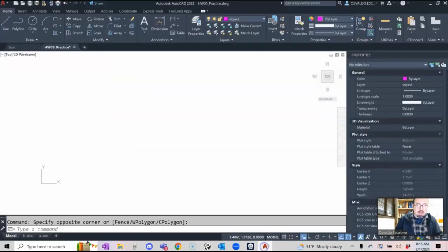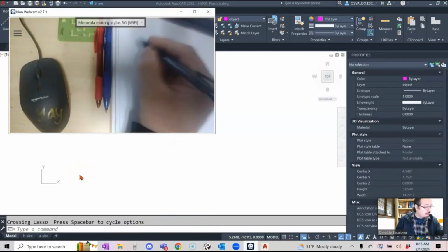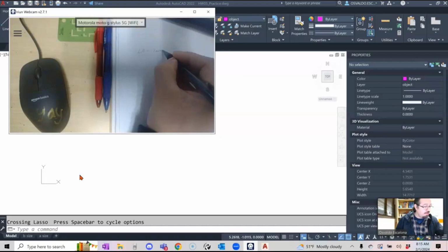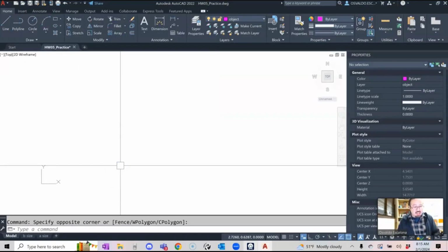If I go here to AutoCAD, the command that you guys want to remember is the command layer. So I'm going to come back here, get a piece of paper, grab your paper, and the command is LA, and it stands for layer. Okay, so keep it there. Layer is something that you can create for a line, for a tree, for a car, for a wall, anything that you want to represent with a color and with certain settings. So we subdivide things for you.